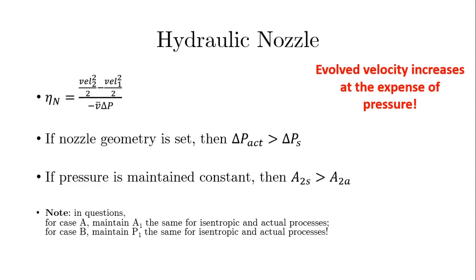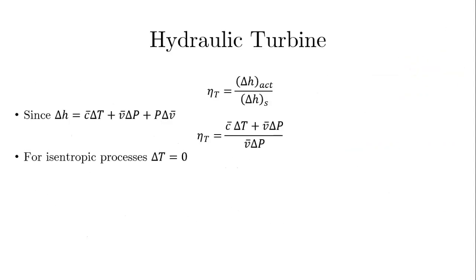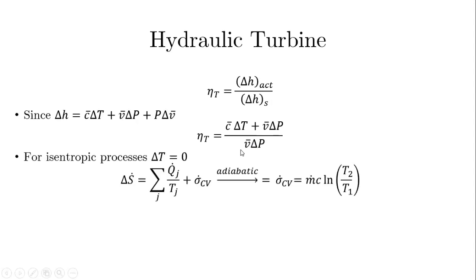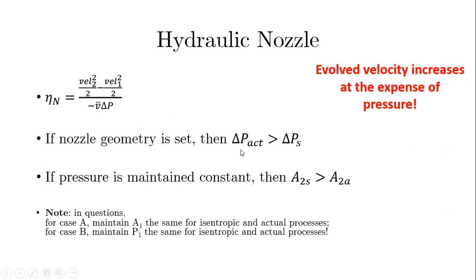Pretty obvious kind of thing to do because you're going to usually use a liquid in a nozzle. So in that case, we've shown already that delta H, as we did over here, delta H at the denominator here, see, delta H under an isentropic assumption is V delta P. So we're going to put that here as well. We have V delta P in the denominator, and in the numerator, we have the velocity, which we're trying to maximize.